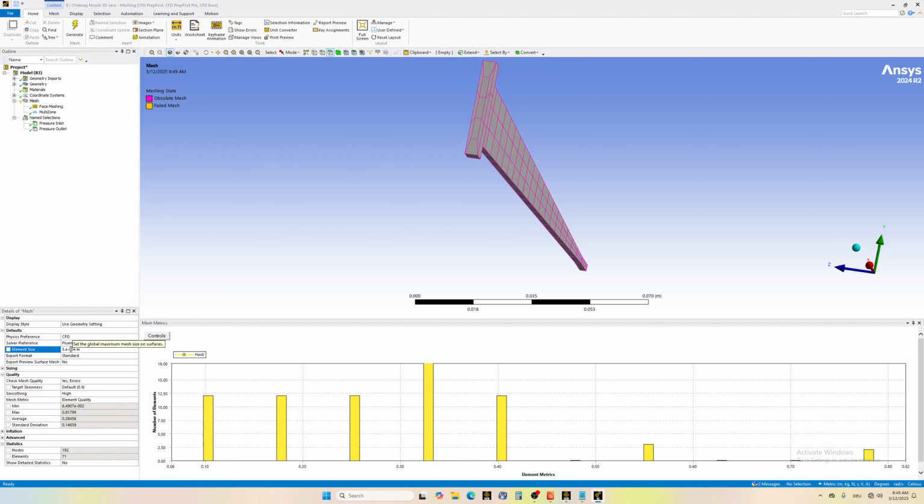So even if you put here a very, very small element size, you will not be able to run the simulation because you are limited. Otherwise, it doesn't really matter. It will work, but keep in mind, the more cells you have, the longer the simulation is. But if it's required to see shocks and small features of the flow, you will need to have a very small cell size.